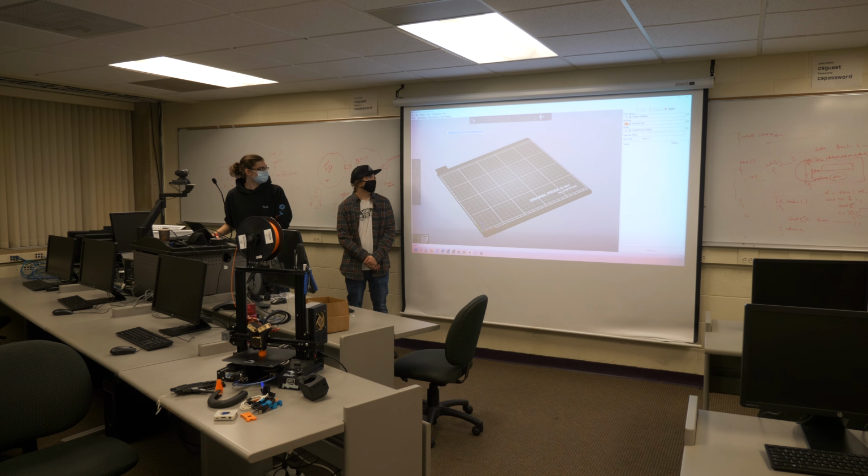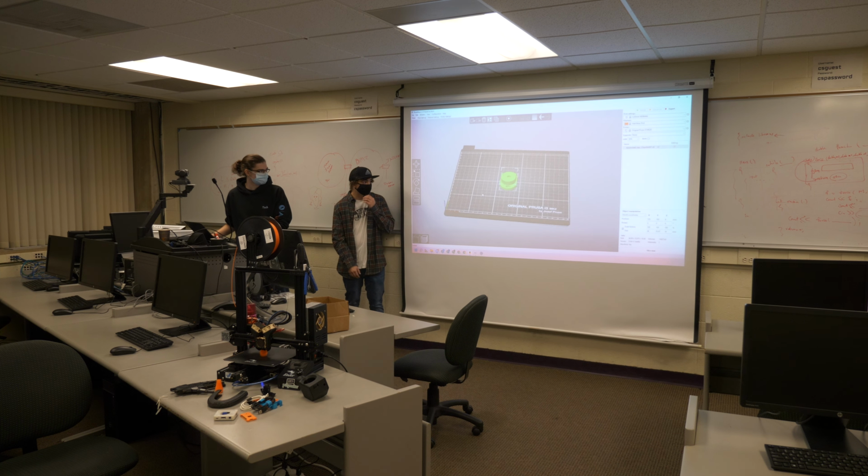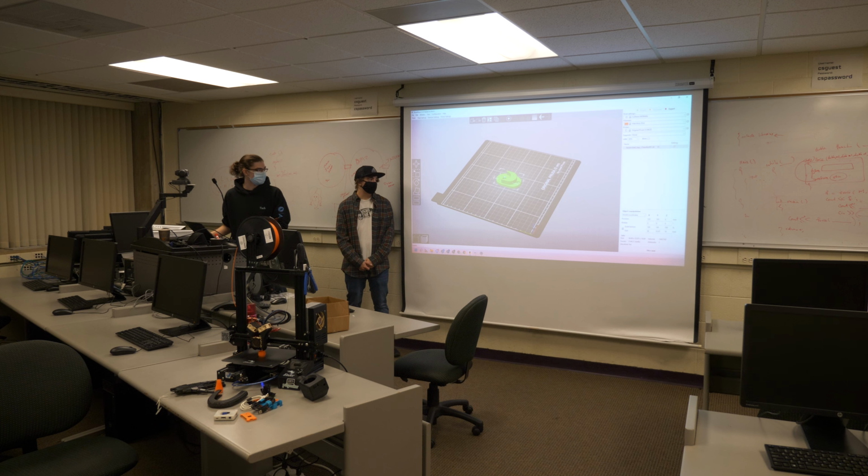I'll do this over my shoulder without being able to see anything. You can import parts saved as an STL, OBJ, those file types, and place it on the bed. You can orient it. So if this part came into the slicer at a 90-degree angle, I would definitely want to move it around, because that's not a viable orientation to effectively print something.